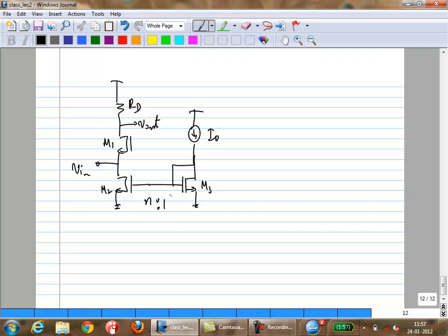Correct? Okay. Now suppose next you open circuit this. Now both those noises are going to flow directly into the output. So you'll have the old Vn out squared when you are calculating the input referred noise current, and you would add the noise of M2 and the multiplied up noise of M3 to that times RD squared. You will have to do that.